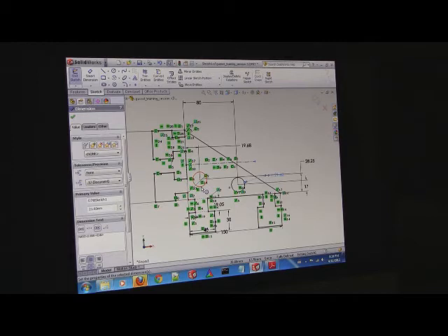Now take a construction line. How do I do the positioning of this? Press on the outside of the circle, and press on that bottom line. Drag that way. And that one is 28.25, from the top point to the bottom point. But you don't have any line selected yet. Is it 17? Yes, 17. Now do the same thing for that one, and that one is 28.25.